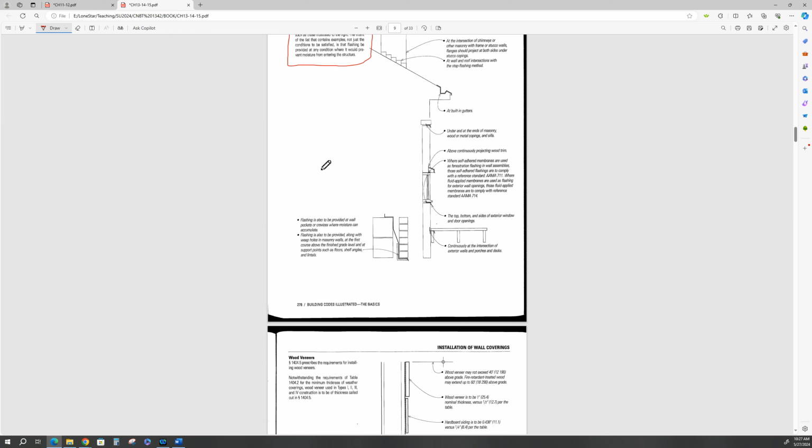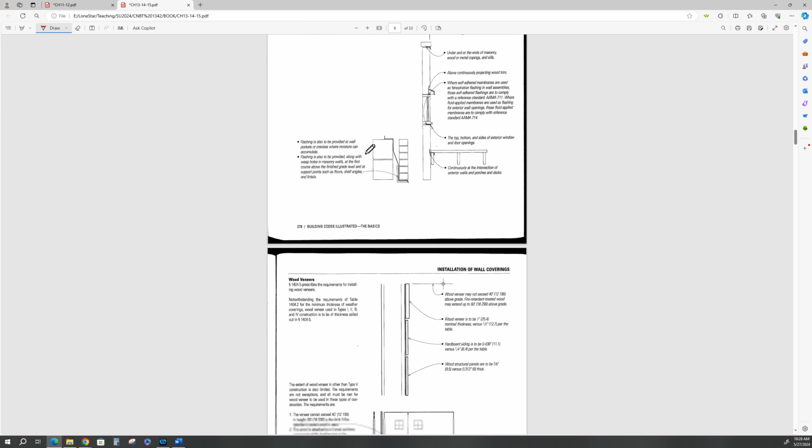If you took my CNBT 13, oh my God, what is it, 14 or 11? Anyway, construction materials and methods. You'll know that I have a real pet peeve about this. The Cypress Center, the RTUs, the rooftop units, they leak like a sieve because they poured the whole upper deck and then they went in and cut holes and then set the dog houses, the curbs on top of that, and tried to flash them. They leak all the time.